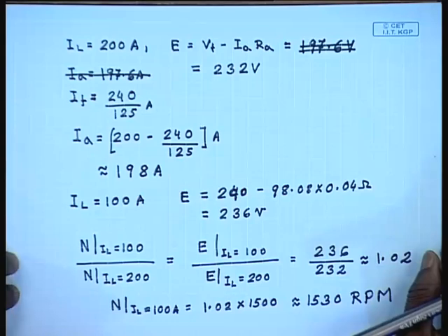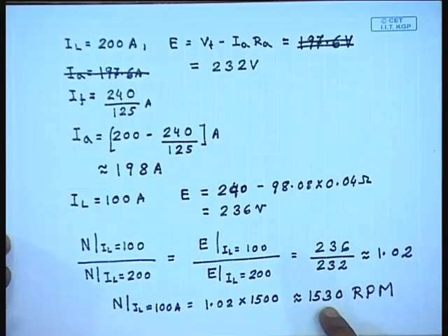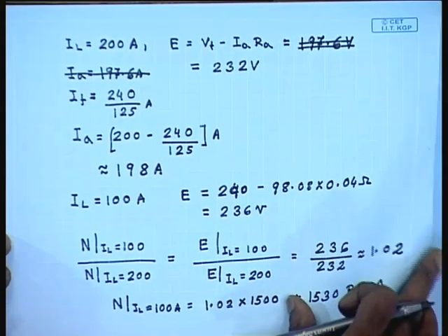So, another thing we observe is that with field control the speed regulation is rather poor. Even for half load reduction, there is a change of 30 RPM of speed, which is not desirable where tight regulation of the motor speed is required.